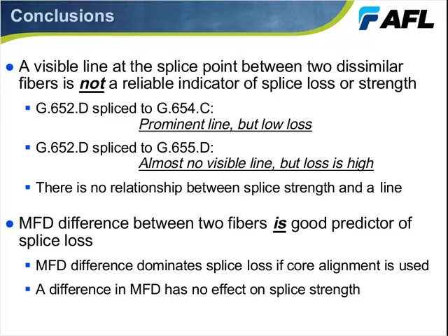Next, you mentioned weak arc power is possible for a bubble. Rarely. It's more likely to cause maybe a little bit of a shadow, but frankly speaking, weak arc power usually, in most cases, doesn't have a dramatic effect on the appearance of the splice. It's more likely to affect the strength.